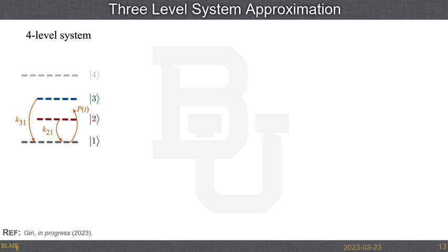And so this is what's called a rate equation approach. So I want to talk about the number of electrons that I have in this top state, and I'm going to look at the time derivative of that. And I'm going to talk about the number of electrons, and so I'm going to look at the rate at which I can populate or depopulate the second state or the first state. So the first approximation you would make would say, well, if I don't have any electrons up in the upper state, I don't have any probability of it dropping down. I won't have any rate down there. If I have a ton of them up there, then there's probably going to be a lot of them dropping down. So I would expect that this rate is going to be proportional to the population that's up here.